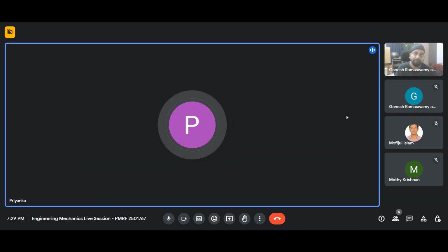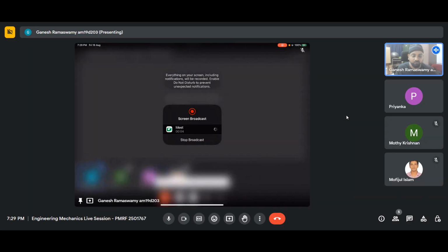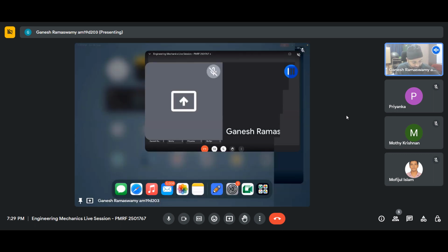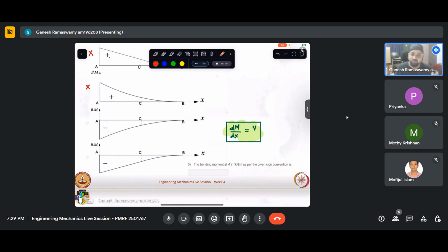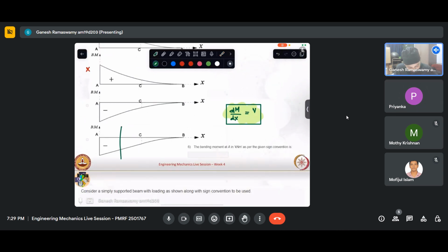Yes, exactly. So that is why this question says qualitative. If it is quantitative, then naturally we cannot use this equation. Instead, we would have to go with the actual equation. Am I answering your question correctly, or you were asking something else? Okay, what you're asking is, if let us say at x equal to some 8 meters, what is the bending moment they have asked? In that case, this will no longer serve our purpose, because this is only qualitatively telling us how the slopes at key points will vary, based on which we have to develop the diagram.